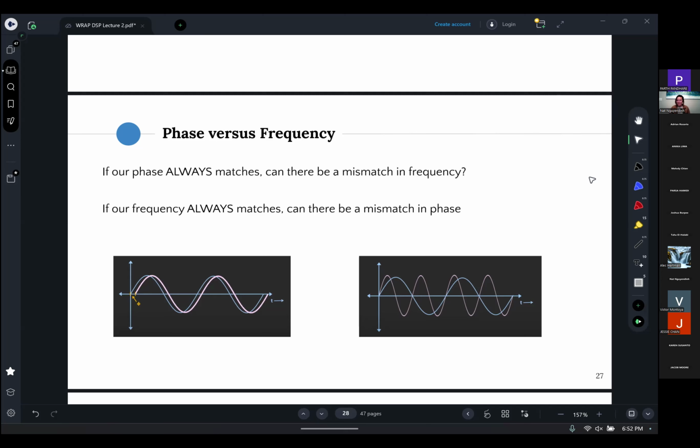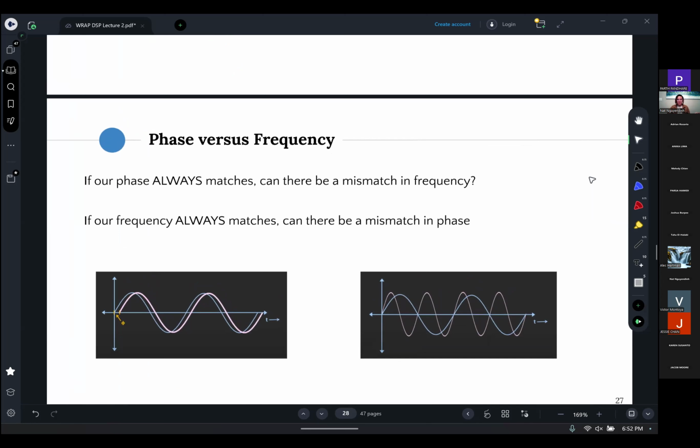Yeah, so that's just because, say the two frequencies could be exactly the same, but if they start at a different phase offset, then they're always going to be offset by that exact amount. But the intuition I wanted to build here was that remember in the previous assignment when we corrected the offset by changing our sinusoids during demodulation to match that phase offset.